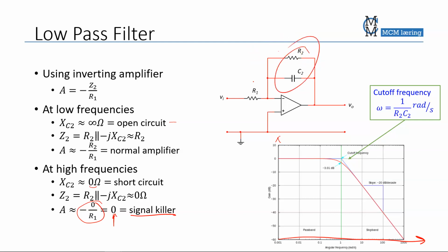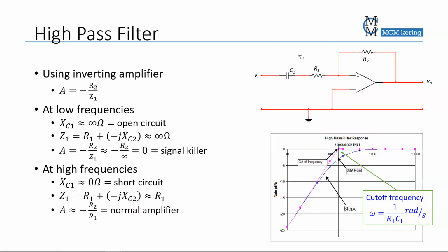Remember, a resistor and capacitor in parallel, where we usually had R2 alone with an inverting amplifier. The high-pass filter has the opposite graph here. You have the cutoff region here and the pass band at high frequencies. So this will keep the treble and cut away the bass of the signal if it was audio. The same thing, the cutoff frequency is now decided by these two components, R1 and C1.